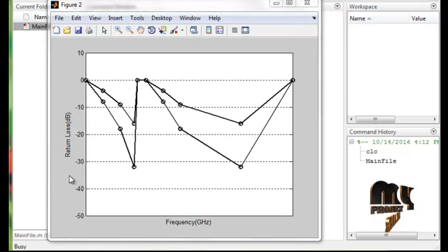In this graph, we also get a return loss, but by changing the dimension of the rectangular patch. First, with size reduction of the rectangular patch we get this, and then we increase the rectangular patch size and we get this graph. Compared to this one, S11 gives a very high return loss, and this one gives a low return loss. The frequency is in GHz, 10 power 9, and return loss is 0 up to minus 50. So the best performance is for FR4 with epsilon r equal to 4.4.